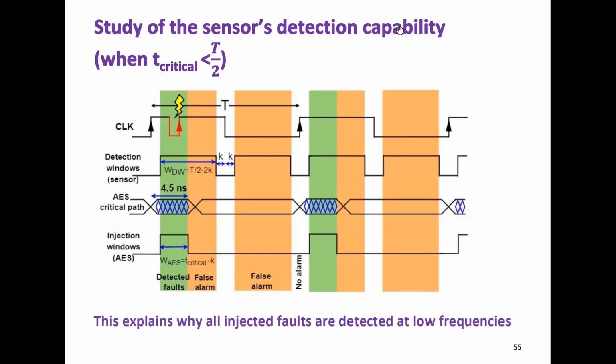Just one curiosity: you do have false alarms. Is there a way, knowing the actual critical path of your target design, to silence them during the periods in which you now know there are false alarms? Because from what you said, there are false alarms just because the fault takes place in a fault-inert portion of the clock cycle. Okay.